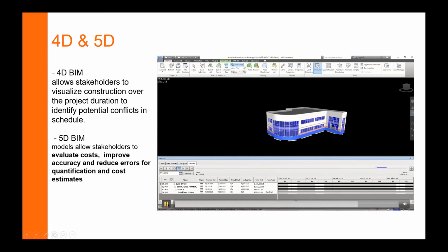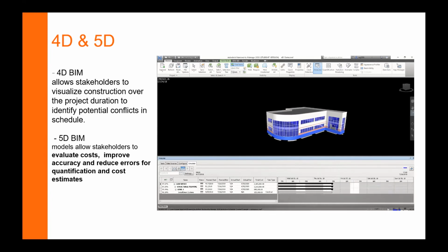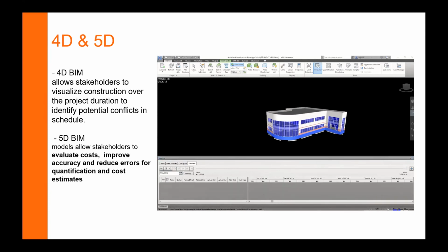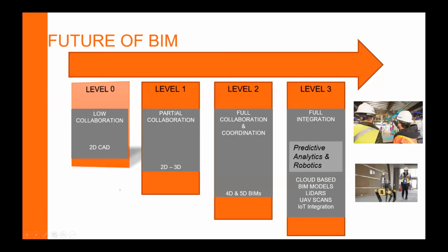And the 5D is attaching the cost to its fourth dimensional schedule. It is no different than a cost-loaded schedule. I'm sure everybody is aware of what a cost-loaded or resource-loaded schedule is. So 5D BIM is again attaching cost to building elements, so you can accurately calculate, quantify, or do cost estimation within the model, quantity takeoff, and there are other tools out there which you can benefit from for the other dimensions.